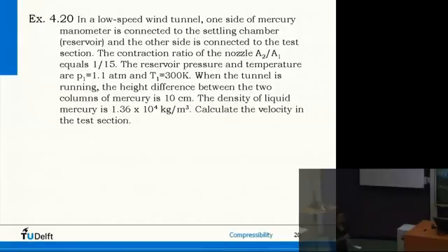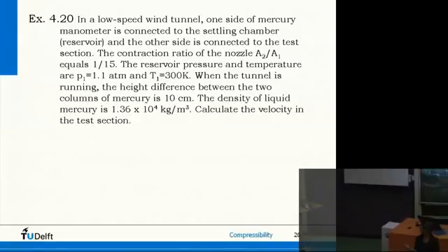Equation of state, perfect. If you think about the isentropic flow relations, P over P and T over T, that's really for compressible flow, where you have significant temperature changes. In incompressible flow, you typically don't have them. So the one I used before for the supersonic wind tunnel will not get you anywhere. But the equation of state, P is rho RT. So if we know somewhere pressure and temperature, we can find the density.